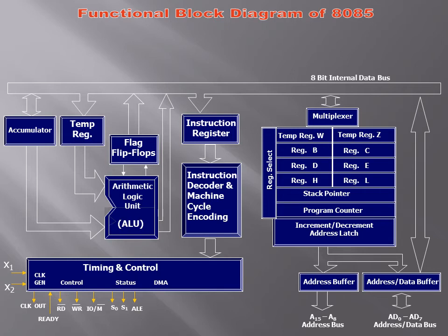So it gives the control to the device, and the data is given to the memory directly without involving the microprocessor operation. That means the data transfer now will be fast. In this we have two signals. The HOLD signal comes from the DMA device outside, and the microprocessor gives the acknowledgement to this HOLD signal, saying that I'm allowing you to transfer data to the memory.